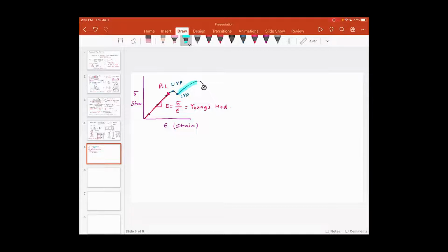And then what happens is, for the same amount of load, the material continues to deform. So which means even though you do not change the load, the material continues to deform, and then it deforms to the point where the necking happens, the localized stress is significantly high, and then you land up with failure and the component fails. Now this is something called as the engineering stress strain.